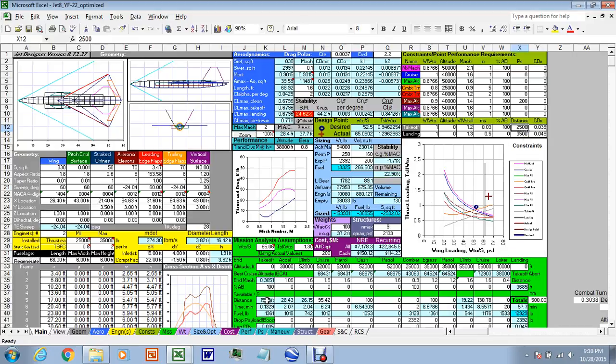Well, we're taking off in 1,500 feet, so that means that we could make this number a lot smaller and harmonize these two takeoff and landing constraints. The way we've got it set up, we're actually calculating the landing constraint by subtracting the takeoff constraint from 6,000. So if I make this 2,000, I'll get a much nicer looking, more harmonious balance between the takeoff and landing constraints.